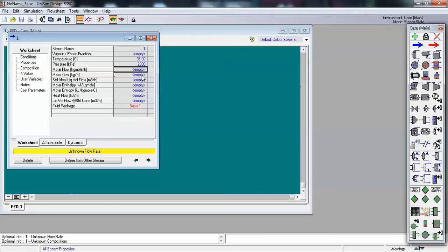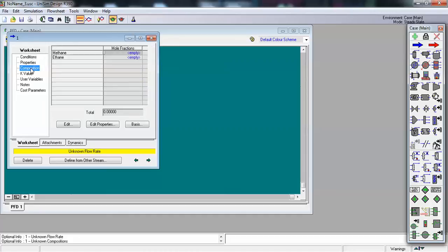Now the flow rate, as we said, is very important. It gave us the basis to be 100 kg per hour. You can come right there. It's a mass flow, so it's 100 kg per hour, and the units are correct. You are done here. The last thing you need to do is to type in the compositions of your components. So for methane, as you can see, before you type them in, it says right there that these are mole fractions.